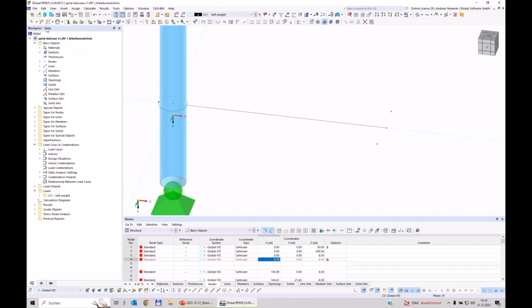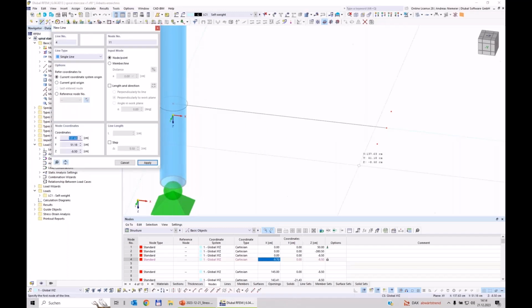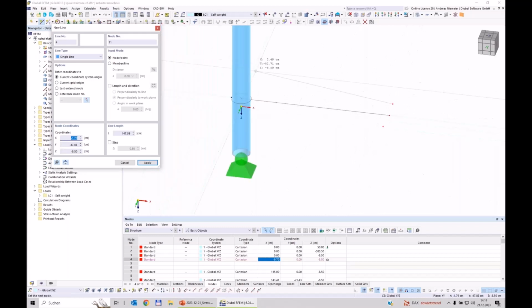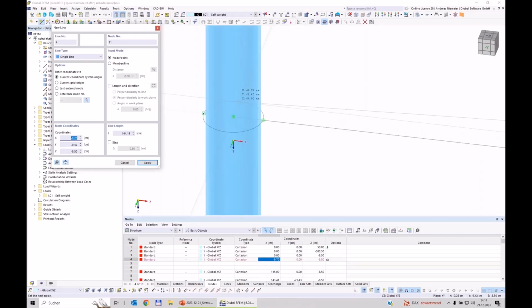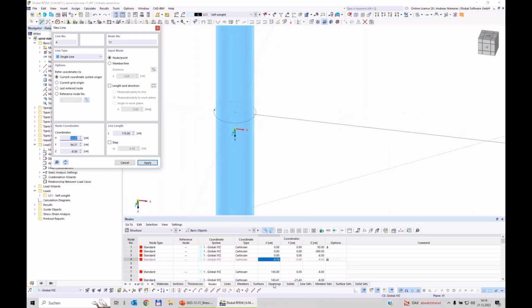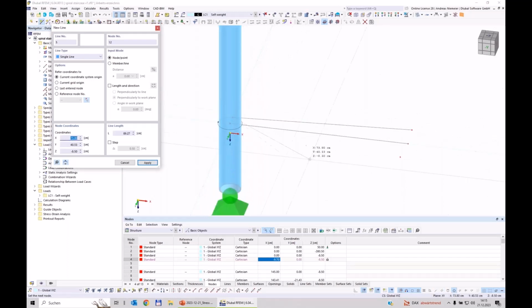In the next part, we specify the outer boundary, or let's say the place of the boundary member of the stair step. So I pick this node, and now I want to pick this quadrant point of this circle line. And you see the program doesn't offer me something. Maybe I can lead you to a new function in our program we inserted in the last weeks, months, such as a status bar with snapping points, with modification commands, with clipping options. But here I'm interested in this point, that I can find these quadrant points of such a circle.